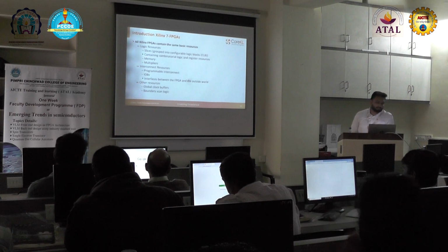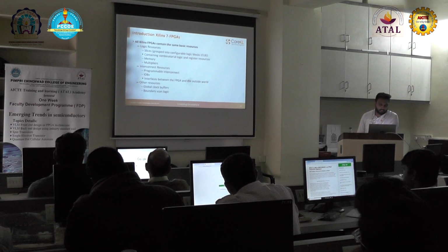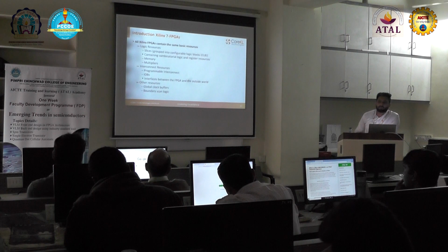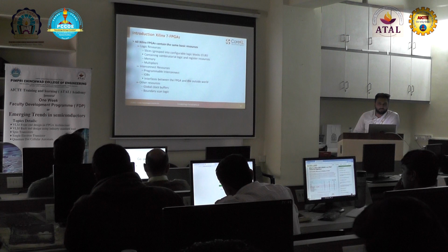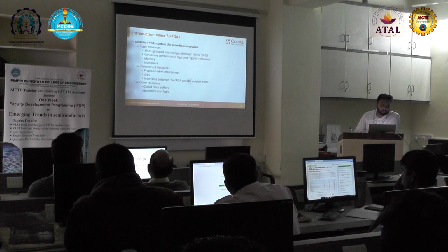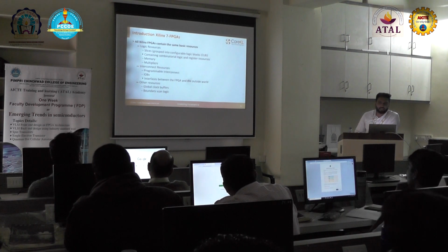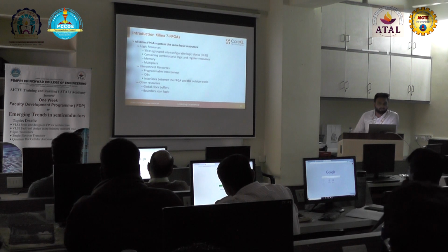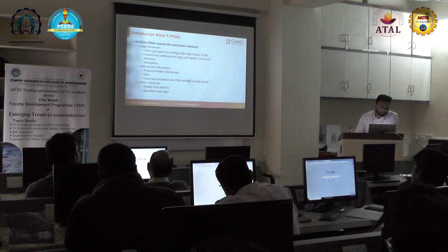Then I am getting into the interconnect resources, where we have programmable interconnects and IOBs. With these programmable interconnects, the input and output from the PS to PL part will be connected to extend the input output peripherals. The IOBs, input output blocks, are the interfaces of the FPGA, and they help to connect to the outside world by using different types of sensors or actuators, like Pmods, GPS, Wi-Fi, those things.